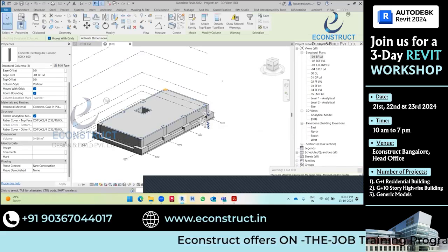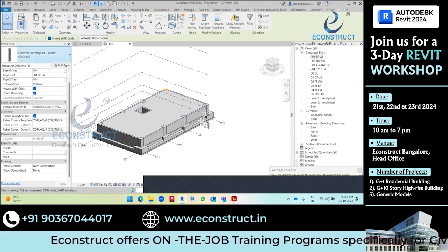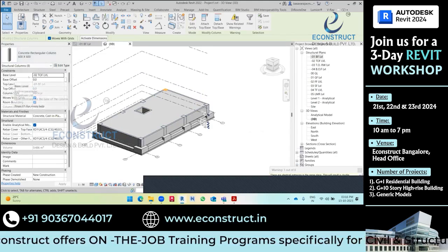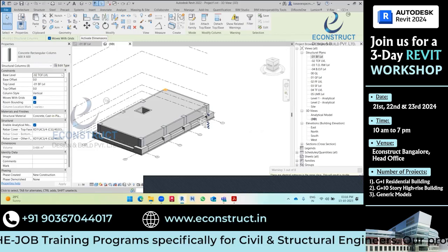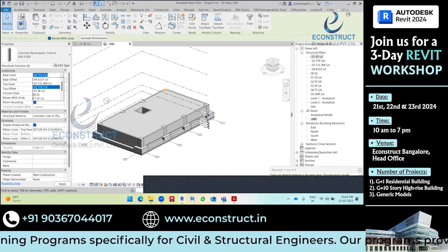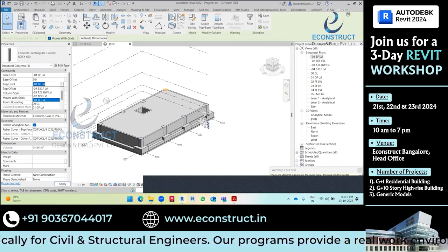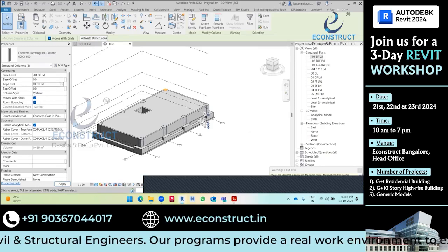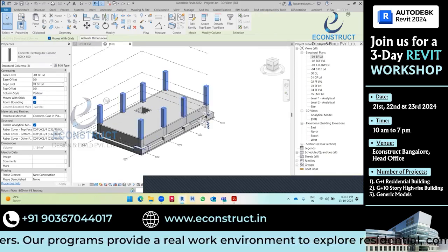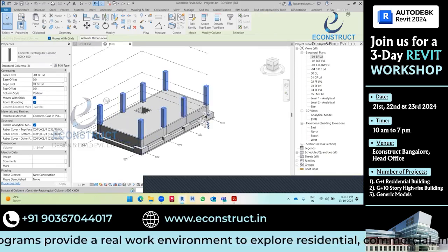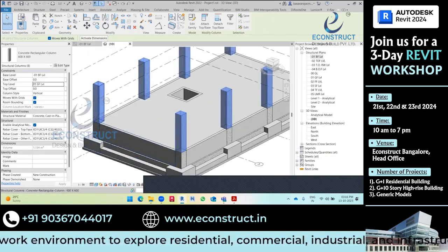After that, don't click on anything, just set the levels. See, now the base level has taken the same top of the footing level only because constraints are on. So instead, change that to the basement floor level, and make the top level the ground floor level. Don't give any base offset and top offset. Click apply. So now the columns are copied from the basement top of the footing level to basement floor level,